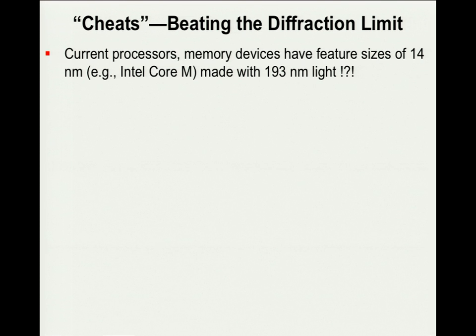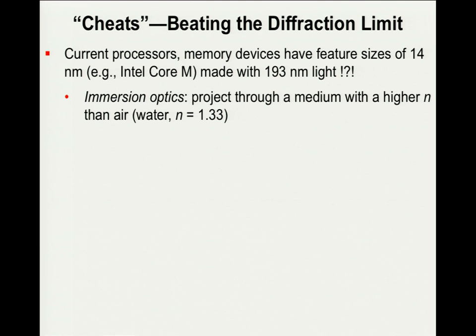So current processors have 14 nanometers, so the Intel Core M is an example. One of the approaches that we use, not me, but people that work in this area, many of you will actually be working in the microelectronics industry because it's one of the top employers of nano engineering and chemical engineering students, is you use immersion optics.